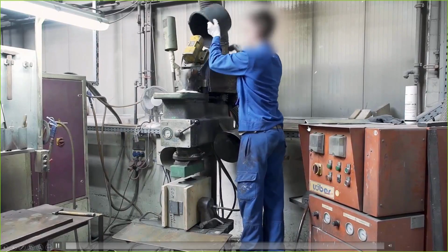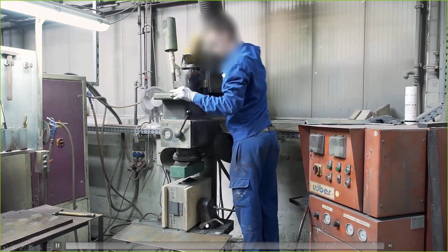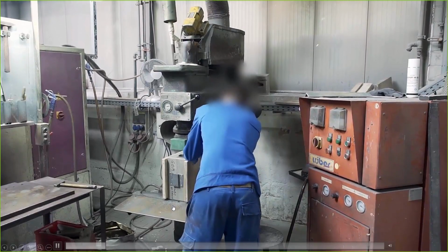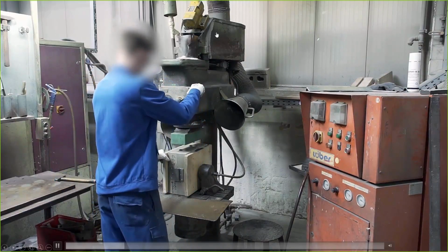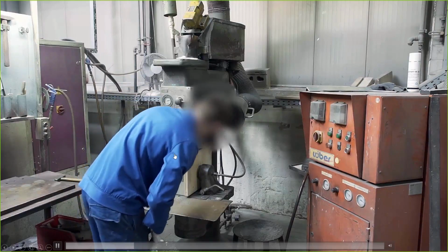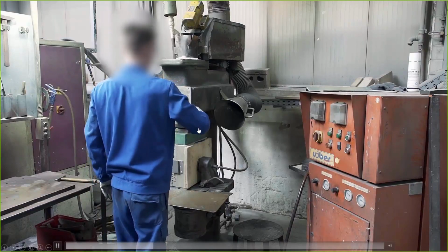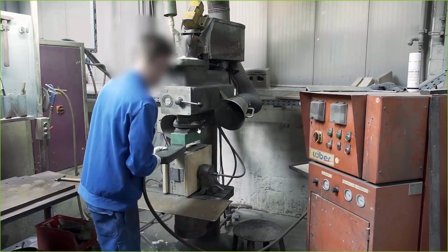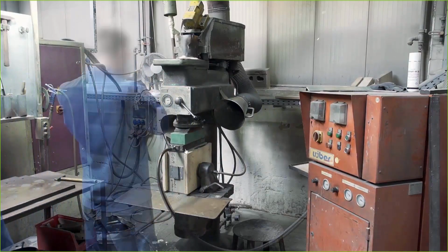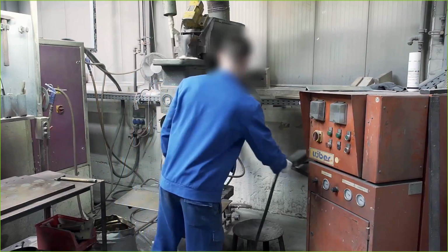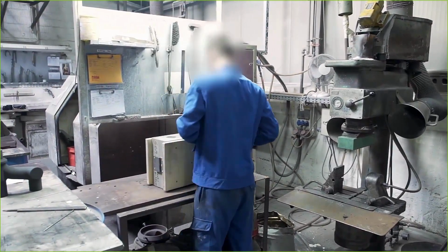Here you can see a typical core shooting machine. Here the core box is clamped on the core shooting machine. You can see this is an assembly situation of both core box halves, and the worker has put the sand resin mixture on top of the machine into the so-called sand bunker. The next step is to fill up the cavity built up by the core box with sand, and this is done with very high pressure, leading to a compaction of the sand. Now the catalyst gas is fed into the sand resin mixture to harden the sand. After a couple of minutes the sand is hardened, and the next step is then to open the core box to get the final sand core.